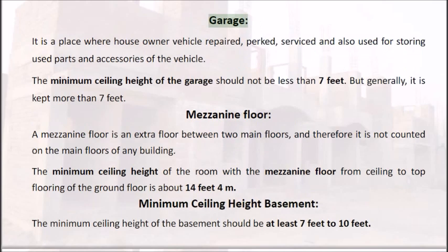Garage. It is a place where the house owner's vehicle is repaired, parked, serviced, and also used for storing used parts and accessories of the vehicle. The minimum ceiling height of the garage should not be less than 7 feet. But generally, it is kept more than 7 feet.